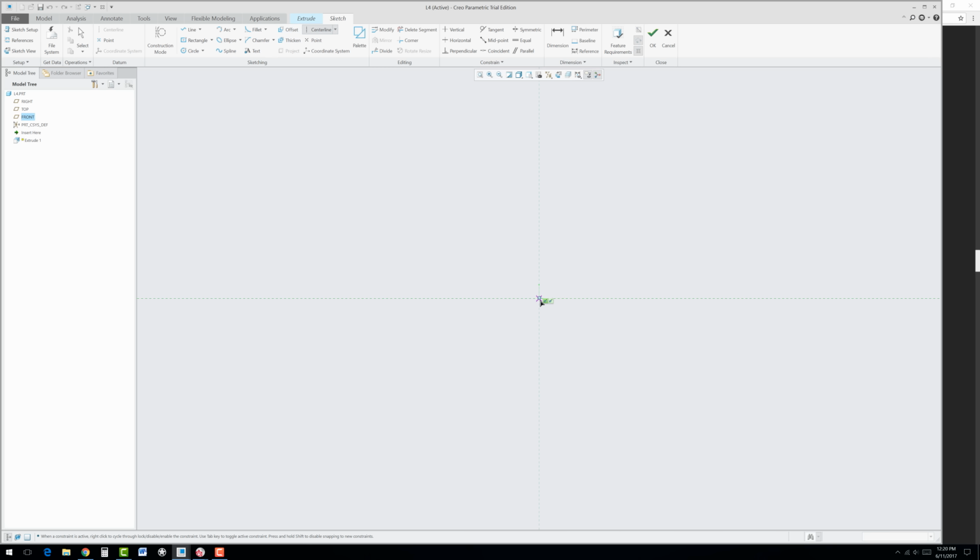Draw a vertical center line and middle click. I would recommend drawing a line, but in construction mode, to give you some bearing. So it's a vertical line, middle click, and just make that about 2 inches. Again, that's just to scale it to size, so it comes together easier. Make sure you turn off construction mode when you're done.